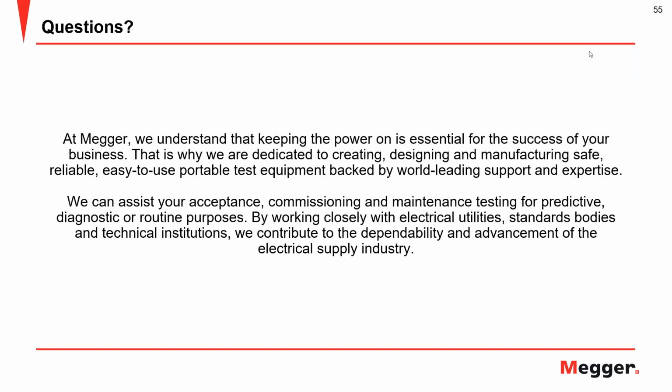Okay, so Henning just touched on this. This rule of thumb is the technology, the one-ended measurement. Now, this number, this is why I said take it with a grain of salt and it's only a rule of thumb. If you have a very well-built XLPE cable, the splices are all built very well, there's no water ingress, we've had cases where you exceed far into higher length, where you were able to measure far beyond 5-6 kilometers.